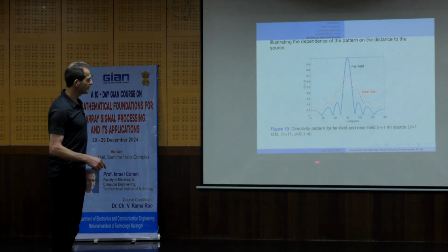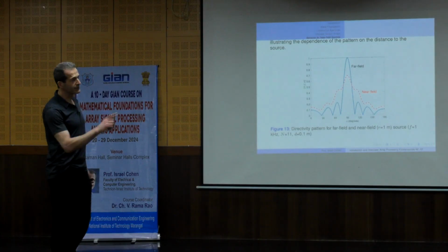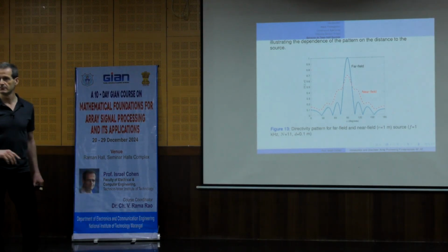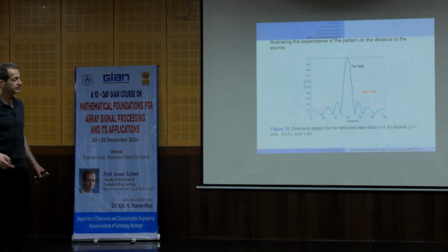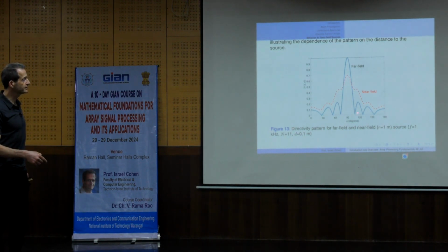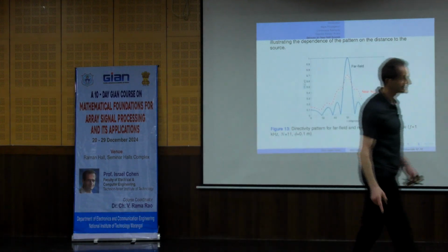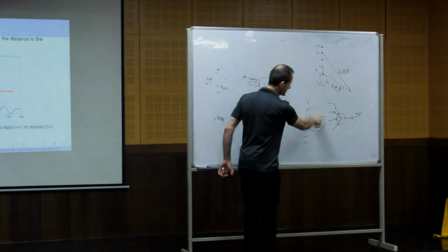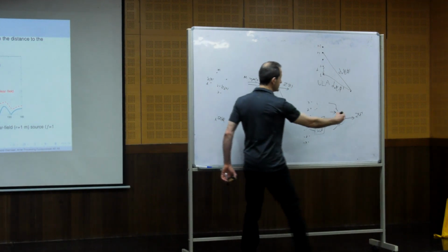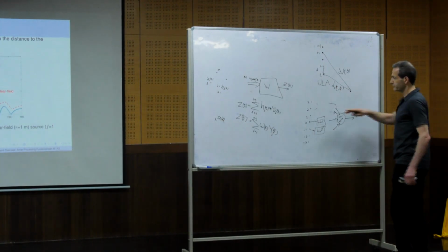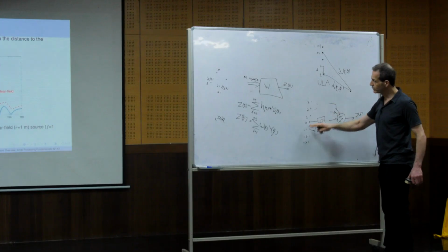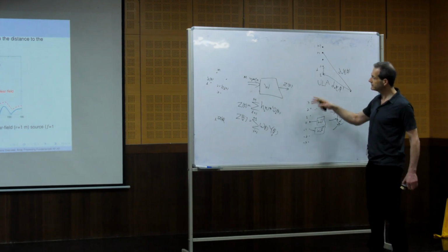If we take the weights constant, 1 over the number of sensors, we will get this directivity pattern. We see it's maximum for the signal that comes from 90 degrees, from the broadside. Of course, because if the weights are all constant, 1 over n, and the far field source comes from the broadside, we accumulate all the signals that hit all the sensors and get a summation that is maximum.